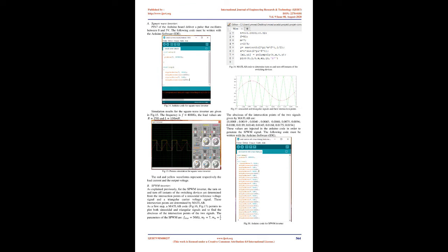A power circuit module. The power circuit consists of the full bridge inverter shown in Fig.1. The input to the power circuit is a DC source, equals 12 V. The full bridge contains 4 MOSFETs, IRF530, and 4 antiparallel diodes, 1N4007.